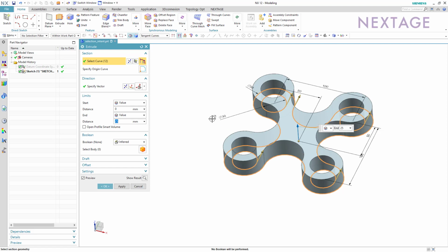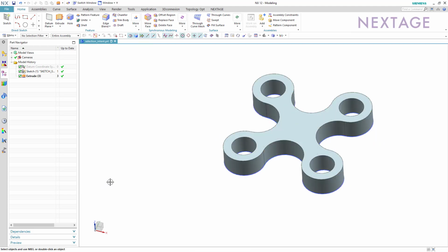The next thing is the robustness, and that's the last factor to take into consideration. Right now I used the follow fillet. So I selected the entire circumference, and then afterwards I selected the circles inside. And I'm going to say, okay, so now I've created this extrude, and now we're going to see how it adapts to changes I make if I, for example, go into my sketch.